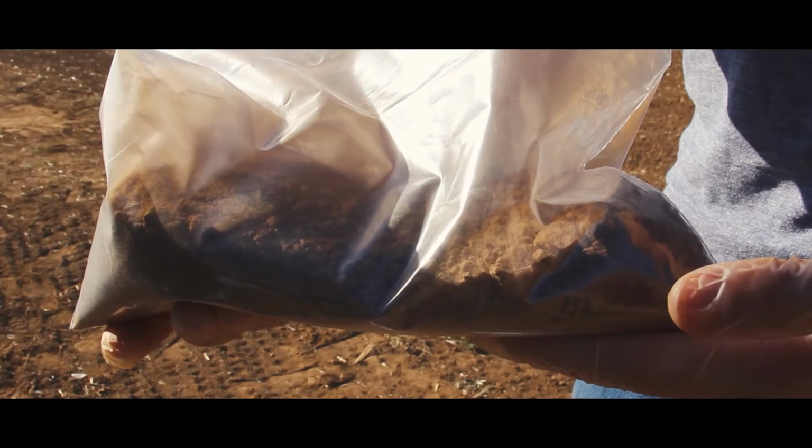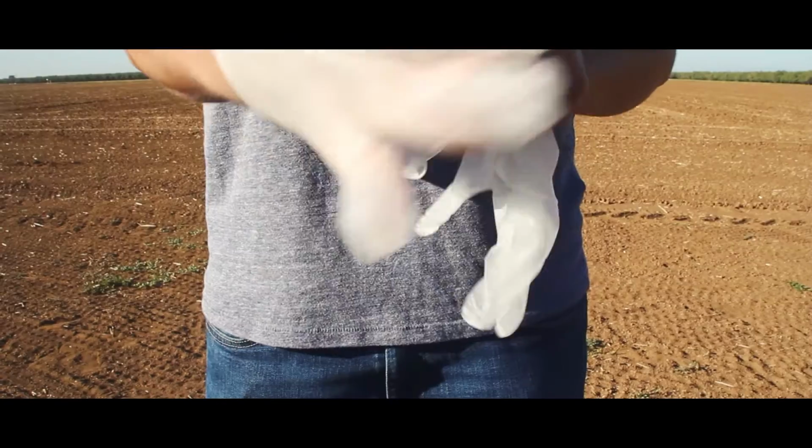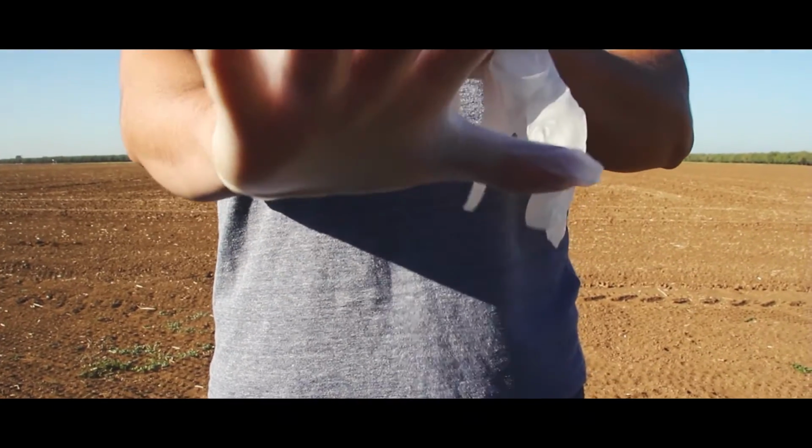Fill the sample tube or bag provided by the contract laboratory with a portion of the soil and securely seal the container. If you're sampling from multiple field locations for different samples, make sure you wear clean gloves at each location or wash your hands between the locations.